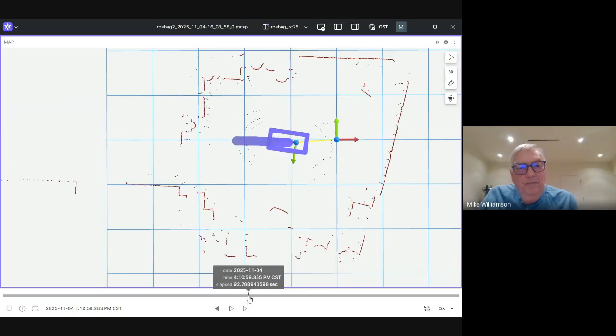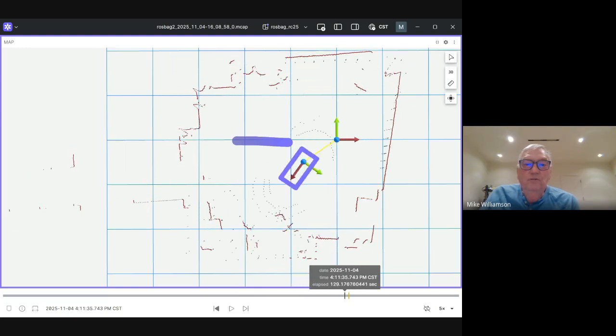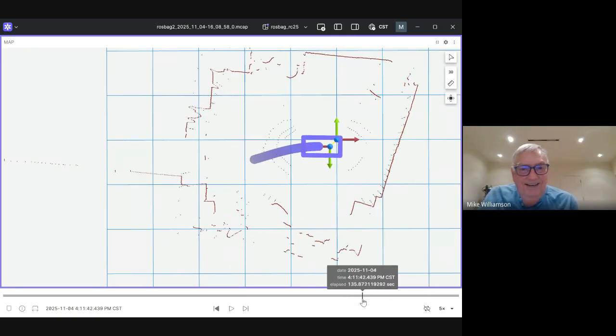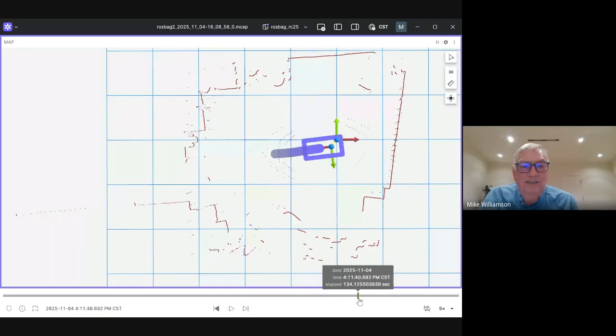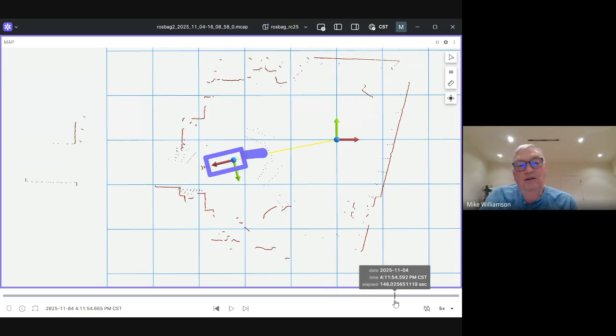And then I start doing a dance, which is basically running a circle, but instead of running it as a circle, I'm running it as a dance thing, because it gives me a tighter radius. I just go forward, backwards, turning the wheels each time. And then at this point, it says, oh, I see the cone. So it doesn't see the cone until here. And then it starts going towards the cone. And then it switches over to manual control. Not me manual control, but my custom software instead of using the navigator package.